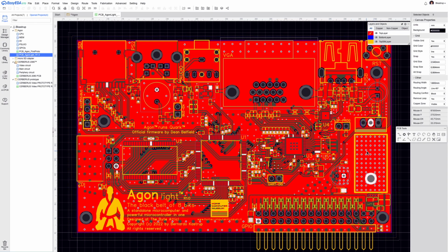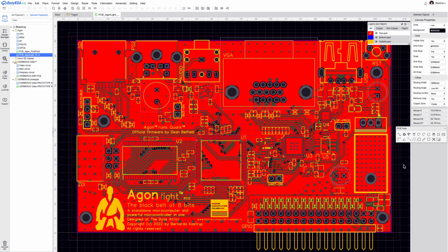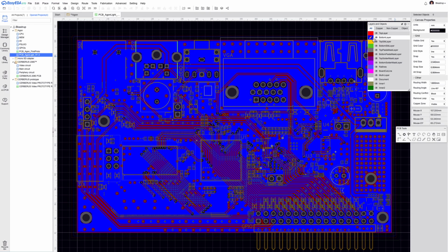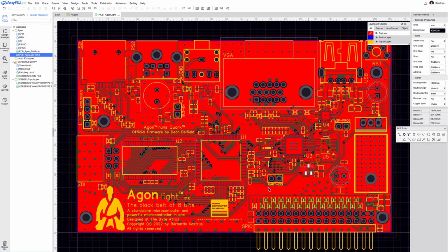So if you have VCC on top, the next underneath needs to be ground to form the capacitor. And then the next after that needs to be VCC again. And then the one after that needs to be ground again. You want to swap out ground and VCC to alternate them as you go down the layer stack. And that's why you have copper flood with VCC on the top layer. Then you have a ground inner plane, then a VCC inner plane, then you copper flood with ground on the bottom layer in blue. That's the idea.